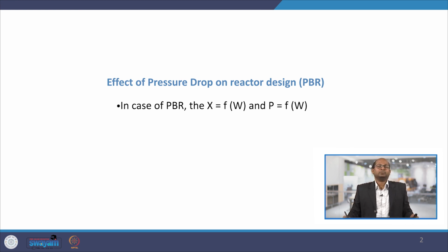Now if we want to design that packed bed reactor, when the reactions take place, we need to get the conversions, rate, concentration at the outlet of the reactor, and other things we need to know. So, let us say the reactor is under isothermal conditions, meaning we are maintaining the temperature constant during operation. The temperature of the catalyst bed or reaction temperature is constant.